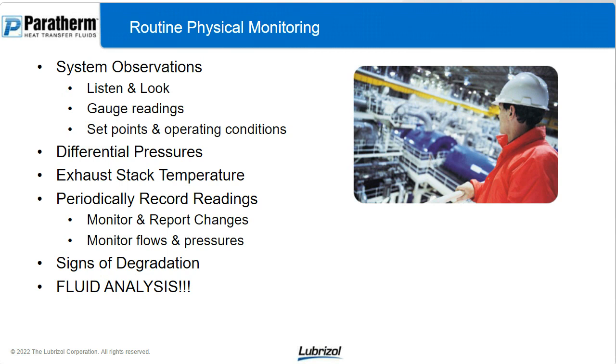The exhaust stack temperature, that's an important one to read too, because the heat that's not going into your fluid is going out of the exhaust stack. So take note of what that is under normal new operating conditions. If that exhaust stack temperature starts to rise over time, that's energy that used to go in the fluid and is no longer doing that. It's going out into the atmosphere. So there's a problem. That's a red flag. So record your readings, monitor and report changes, know the signs of degradation, and get your fluid analyzed.